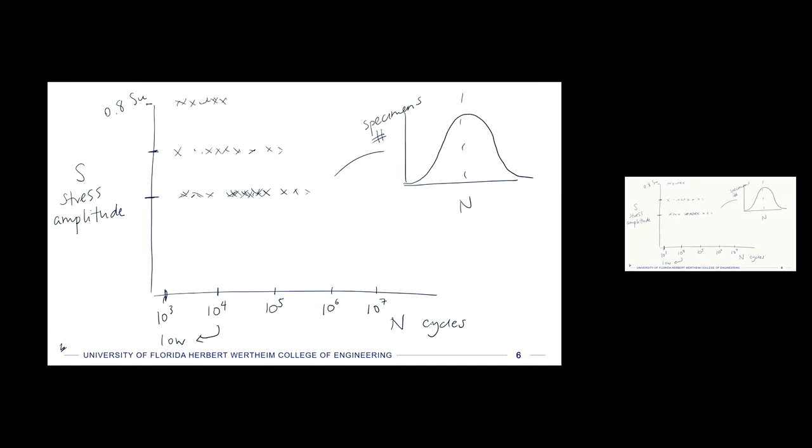And then as we go out at lower stress levels, the data starts to spread out even further, like this. Sorry, my X's are getting messy. We go further and further, and then we really don't get many data points at some low stress amplitude. And so how these SN curves are created is they take the center of each distribution and connect it with a smooth line.